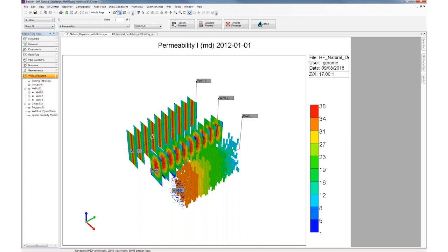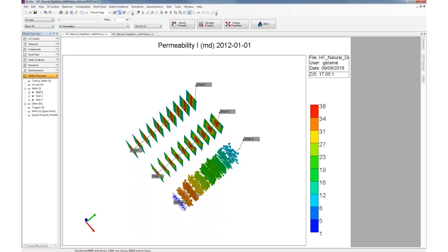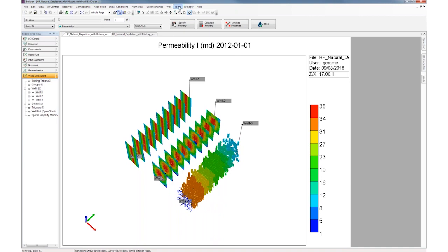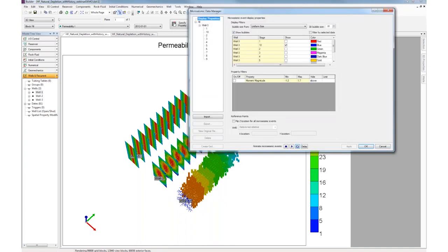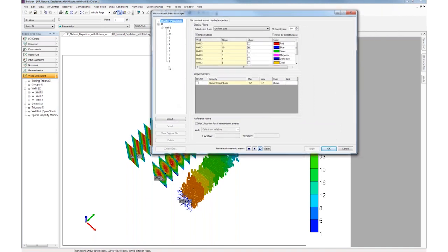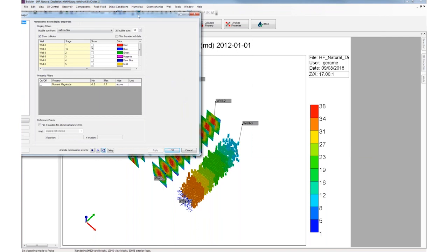And lastly, I showed you how to do the planar fracture template and also importing the fractures using a hydraulic fracture simulator. Lastly, we can also import microseismic data into our model and then create the complex fracture network according to the microseismic events that we're finding inside our data. To import your microseismic data, you would go into Tools, Microseismic Data Manager, and you would click the import button to go ahead and import that data. I've already imported microseismic data for my well number 3, which you can see here in the background.